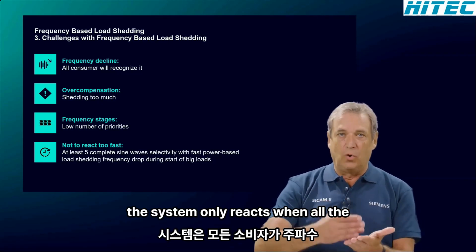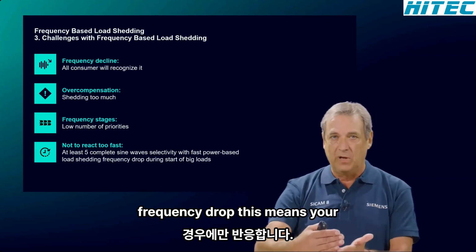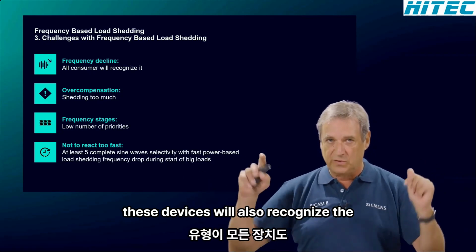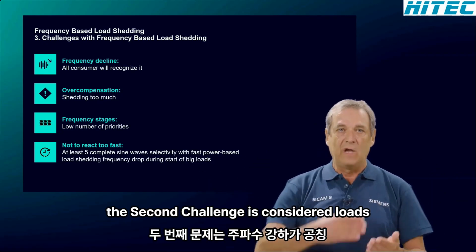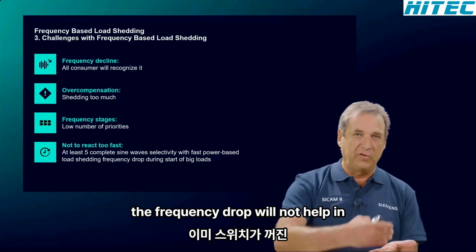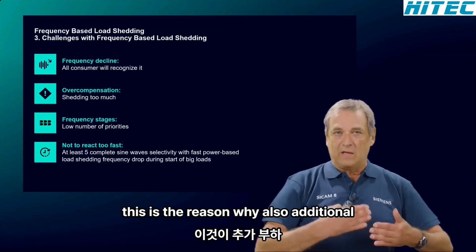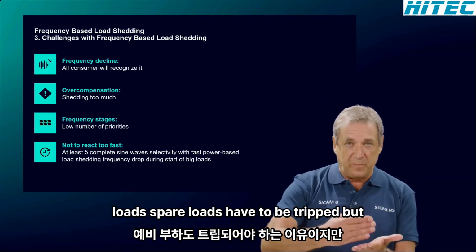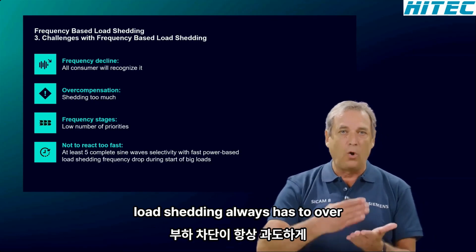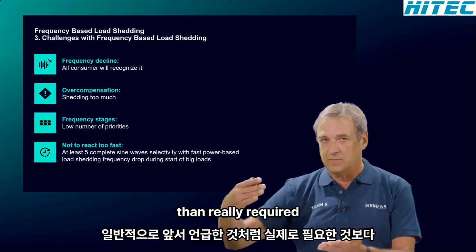First, the system only reacts when all the consumers also have recognized the frequency drop. This means your computers, your variable speed drives, all these devices will also recognize the drop. The second challenge is that loads which were already switched off before the frequency drop will not help in restoring the nominal frequency. This is the reason why additional, spare loads also have to be tripped. But this also means that frequency-based load shedding always has to overcompensate. You switch off more loads than really required.